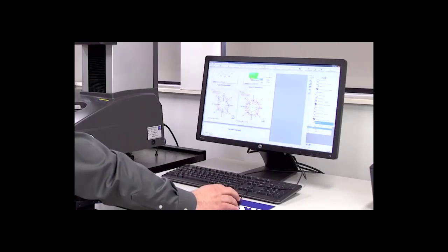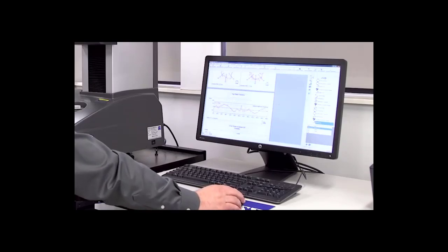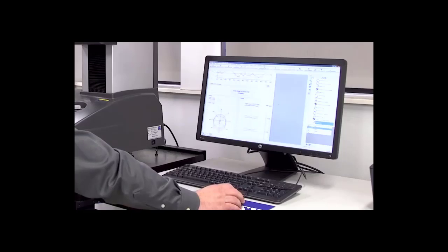Also, we have measured the cone roundness. This is when we turn the stylus at an angle normal to our surface. This is our bore ID roundness. Also, we look at our top plane flatness. We can see the flatness and the values there as well. And from here we will also measure coaxiality at a couple of different points and be able to do that in the report all at once.